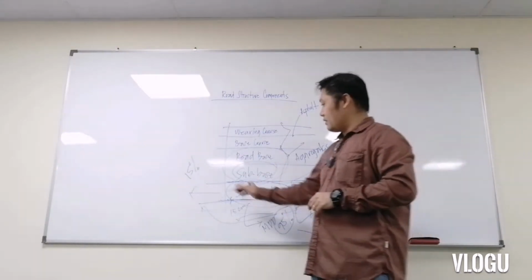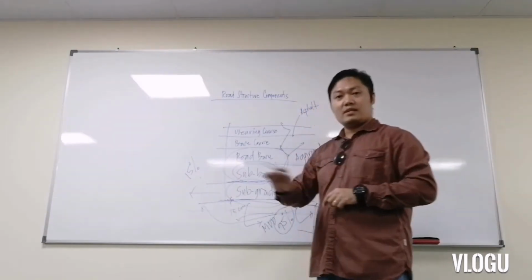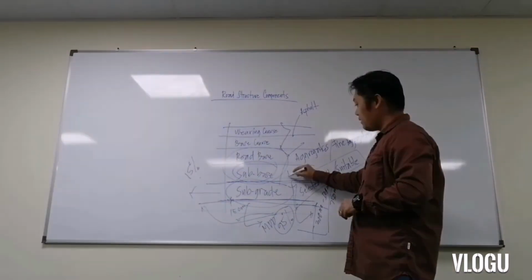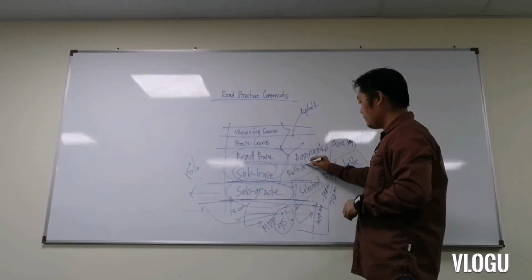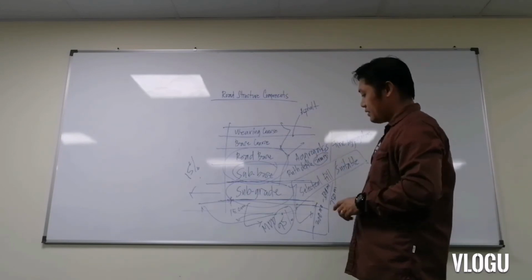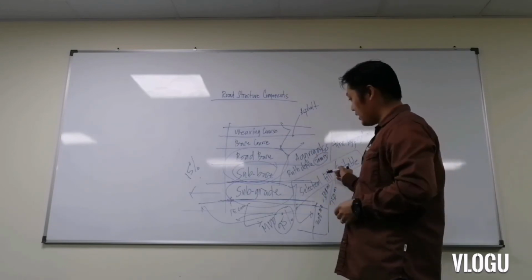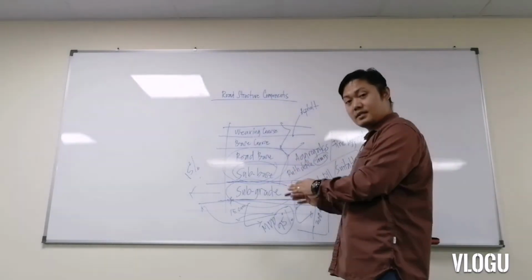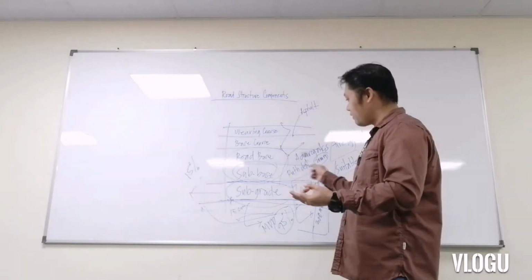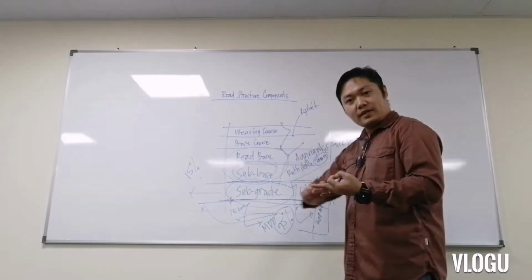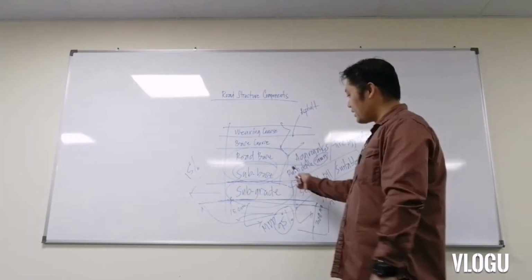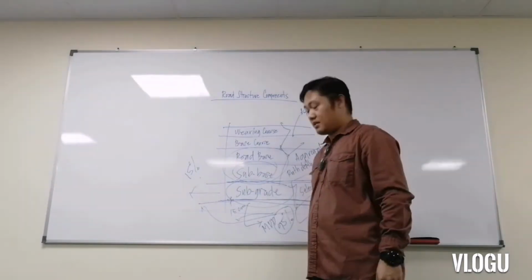The maximum surface evenness requirement for the straight edge is 20 mm. That is 2 cm, and if it is within the tolerance, so we have the MDD, we have the CBR, and we have conducted the surface evenness test, or straight edge. That's the time that we can lay the next succeeding layer, which is known as the subbase.